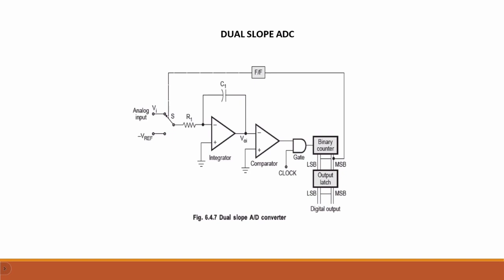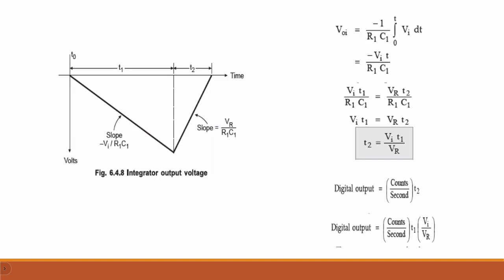In the second waveform, we are seeing the waveforms. While giving the plus Vi voltage, we will get a minus Vi in the integrator. So it will produce the ramp down signal. While giving minus Vref voltage, we get the ramp up signal in the output of the integrator.